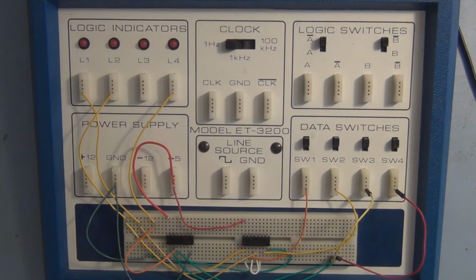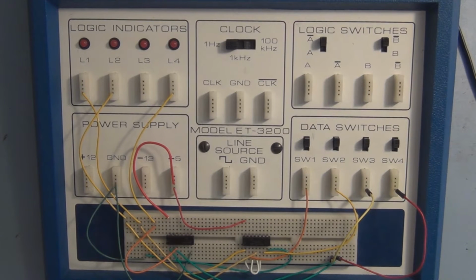Up to this point, the digital logic circuits that I've covered are considered combinatorial logic circuits. And what that means is that the output level at any instant of time is dependent on the input level at that instant of time. So if we change the input, the output is immediately going to change. And this is a characteristic of a circuit that has no memory. So the output is not being determined by any prior state that the circuit is keeping track of. So as soon as you change the input, the output changes.